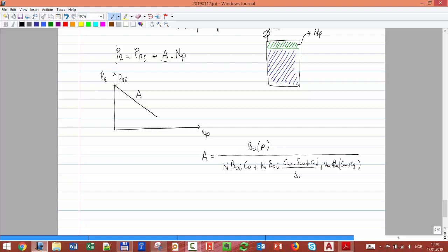If I make my material balance equations, I know what I'm taking out, only oil, and I am assuming both of them expand. This liquid is not incompressible. If I put pressure on the liquid, it will have some compressibility. These are the C's that are indicated here. At high pressures, this C is compressibility. I have compressibility of oil, compressibility of water, and compressibility of the rock. When I apply pressure on the rock, believe it or not, there will be some, very little, change in volume.